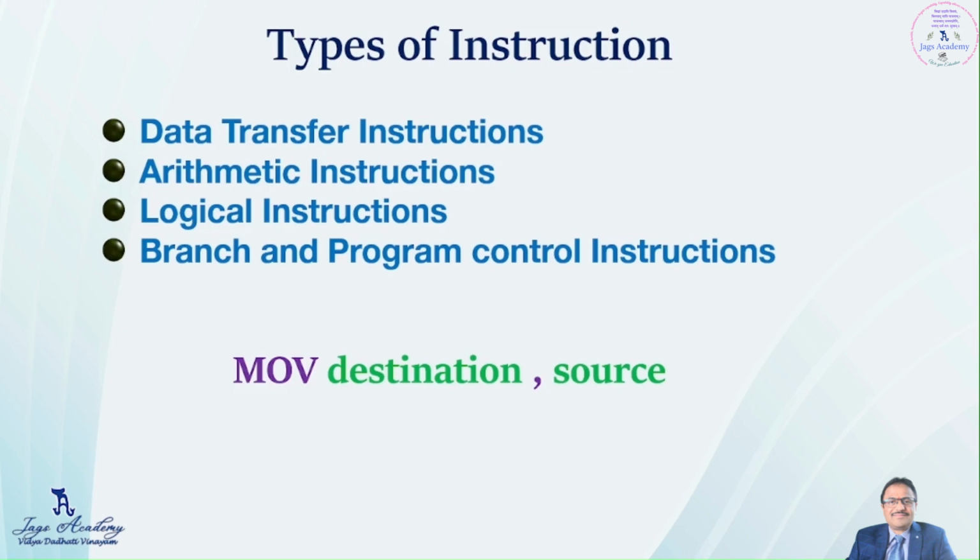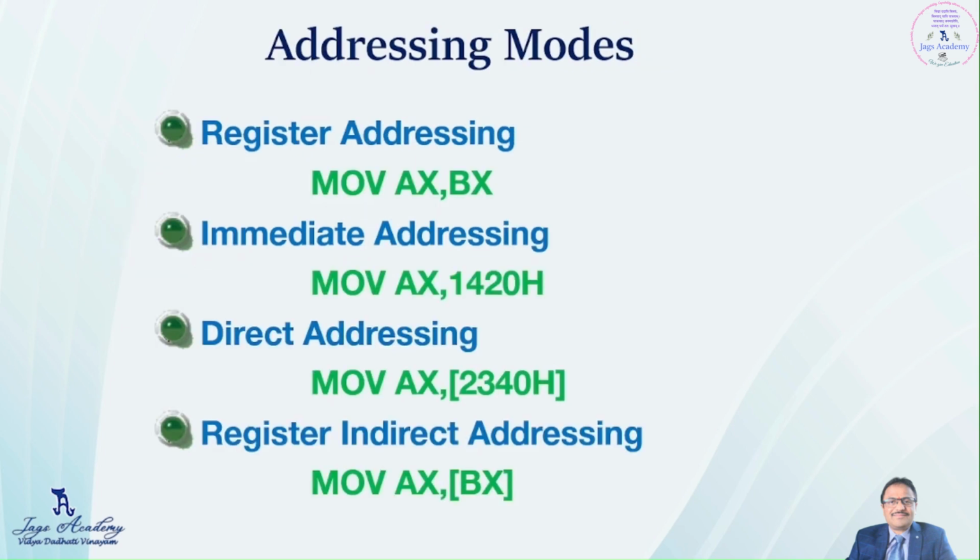We have already discussed types of instruction. We have already discussed something called addressing modes. What are addressing modes? I have informed you in my previous class. Addressing modes tell you how the data is called, how the data transfer is happening, whether data transfer is happening between memory to register or register to register, or there is a data transfer happening with an immediate data written in the instruction itself, right? All these things I told you. So all these 4 we have discussed in our previous class. Hope you remember this. Okay?